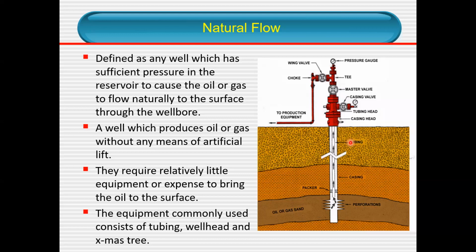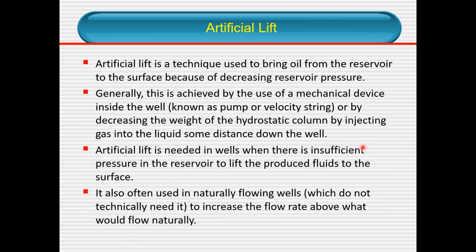But most of the time, when you start flowing this crude oil naturally, you are going to have a deposition of all these solids: wax, scale, asphaltene. Can you avoid this wax, asphaltene, scale, and naphthenate? A definite no. Why am I saying definite no?